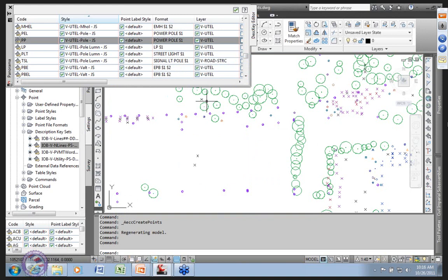One of the great things this allows you to do is this idea of a symbol set, of which you're seeing a little piece, where the graphics can be changed but the names remain the same. That is one of the wonderful things about model-based software: I want to put in a utility pole, and I can determine what it looks like and use the same name, but change what that utility pole looks like to whatever my client wants.